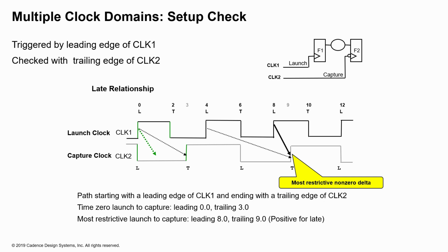When you have multiple clocks, the capture flop is where you need to look at doing your setup checks. So even though there is clock 1, clock 2 is the one that requires the safe storage of the data into flop 2 here. Therefore you need to make sure that when the setup checks are run, the setup check is happening on flop 2 and not flop 1.